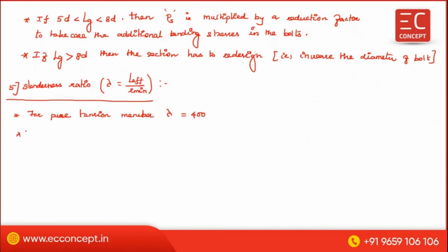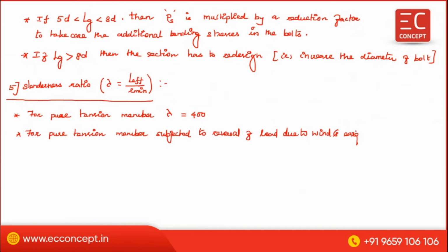Next, for a pure tension member subjected to reversal of load due to wind and earthquake, it is equal to 350.